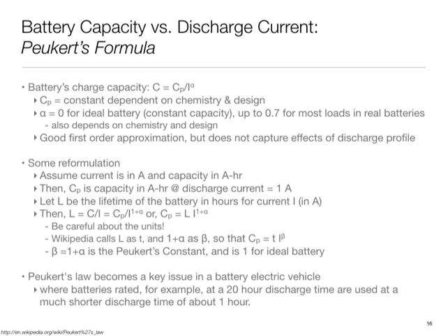Okay. Modeling voltage is much harder, and therefore all these models just assume that voltage remains constant, and then when the battery dies, voltage just plummets. In reality, voltage degrades, and therefore for the same power you need more current drawn from the battery. Going back out here, L is going to be equal to C over I, and then with some plugging in, you end up with Cp being equal to L times I to the power 1 plus alpha.